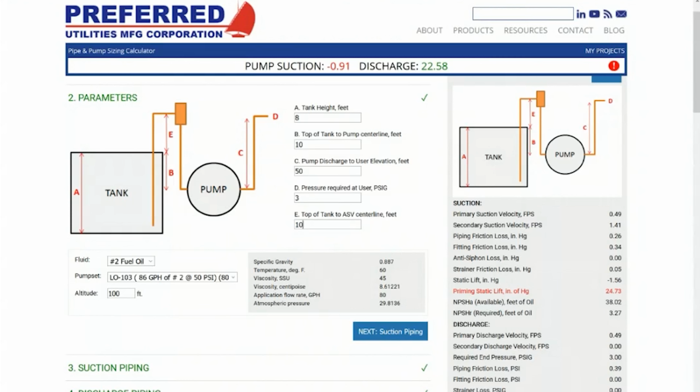But bear in mind, you can have very high suction at the top of that up and over, and the suction can be so great that you actually vaporize the number 2 fuel and cause it to bubble up there. That's right. In extreme cases, we can have real issues on that run of piping. And in fact, one of the other problems, if that's not fully purged and manually primed on startup, is that the horizontal run of that up and over can be partially filled with air because it's very hard to bring all of that air out of that section of pipe down and through the pumps.